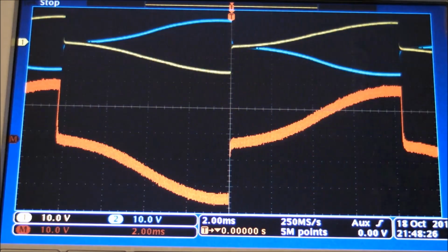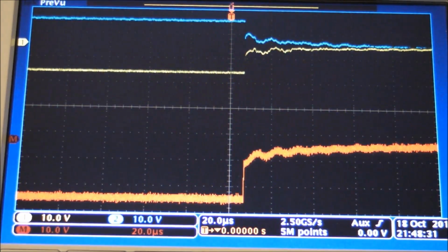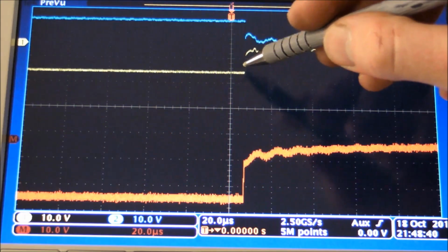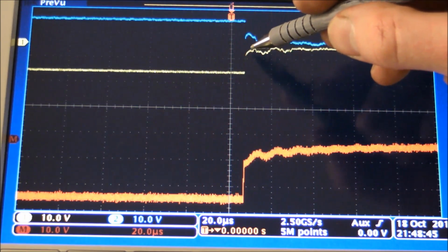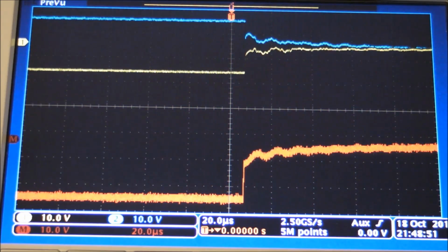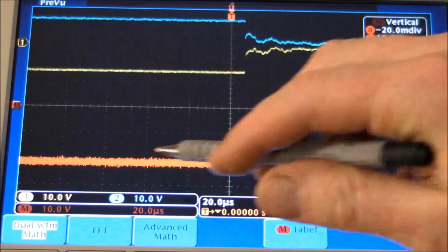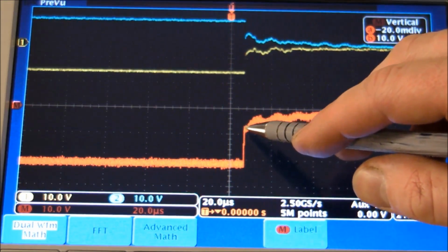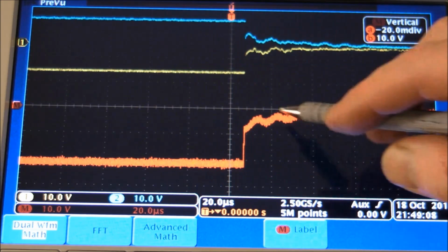So that's the wide view of it. Now if I zoom in, then we can actually see the 100 kilohertz oscillation of the primary tank circuit, and you can see how the voltage, or at least the magnitude, goes down very rapidly to only a few kV per channel. And let's see the math. Let me put that on a better scale. There we go. See, the voltage drops from 20 to about 8 kV, and then oscillates a little bit as it dies down to 0.